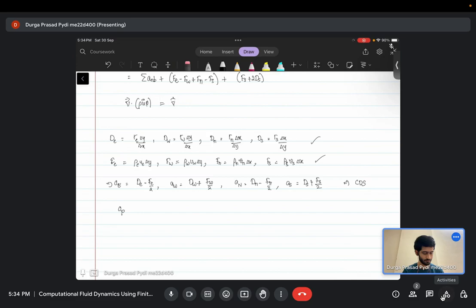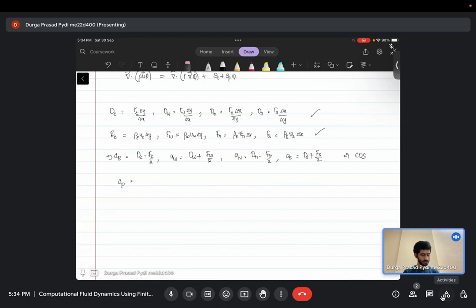So we have del dot gamma del phi, and if the source term is also present, so say we have something like SC plus SP phi, so we have linearized the source term already and it is of this particular form. The first step is we get the diffusion coefficients and then convective coefficients, and then we write all the A and B's for series or in any general scheme that you do, and then your AP is expressed as sigma A and B. This is what we were doing previously.